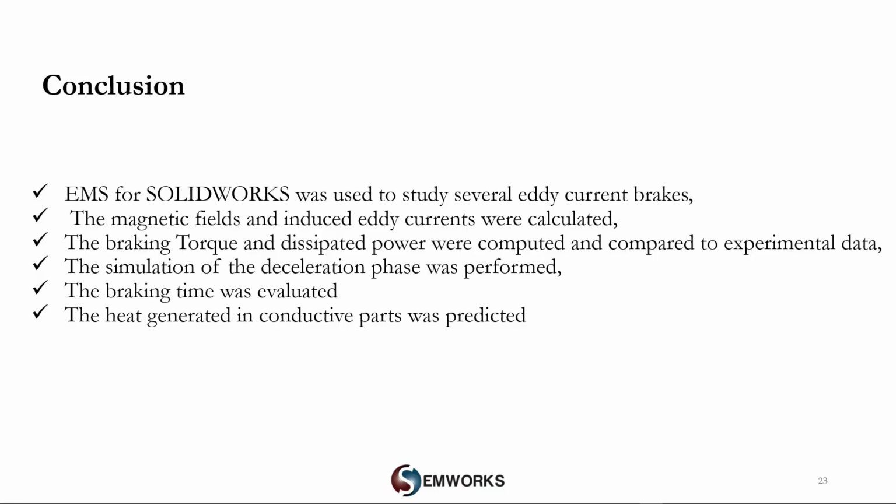Now back to finish our presentation with the conclusion. As we saw, EMS for SolidWorks was used to study several eddy current brakes. We performed the simulation of permanent magnet, electromagnet, and hybrid eddy current brakes. The magnetic fields and the induced eddy currents were calculated. We got the results of braking torque and dissipated power versus several scenarios, and we compared some experimental data. The braking time, I mean the dynamic behavior of some of the braking systems, was evaluated.